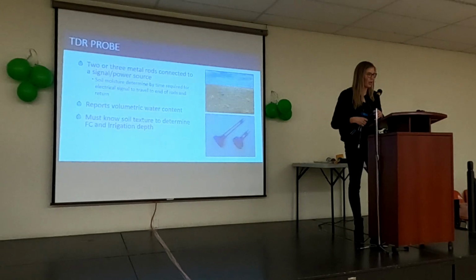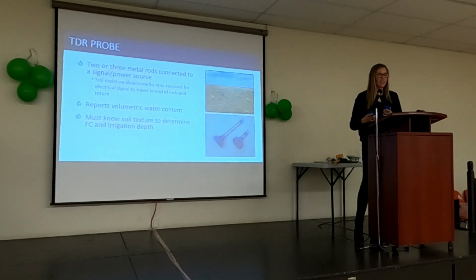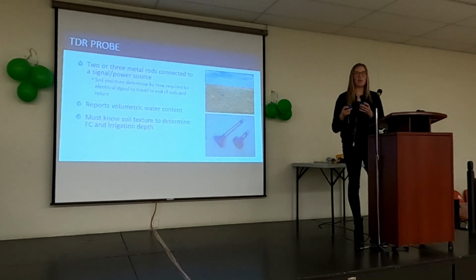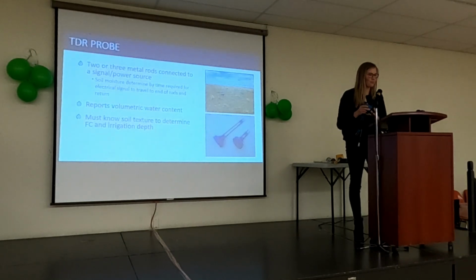It will move slower. So these are Sensiterra brand TDR probes, and we usually insert them in pairs at 2 different depths. So this one's a 6-inch, this one's a 12-inch, so that we can make sure we're hitting the shallower and deeper parts of the active rooting zone throughout the field season.